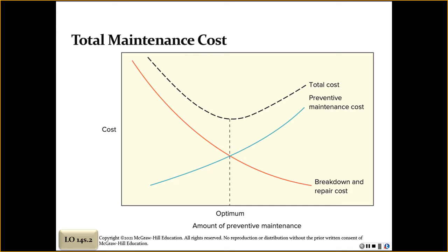To be proactive means that the maintenance is dealt with by scheduling it periodically. So you might have preventative maintenance or preventive maintenance, where you're scheduling every week or every month when maintenance is going to occur, just to lower the downtime of any type of equipment.